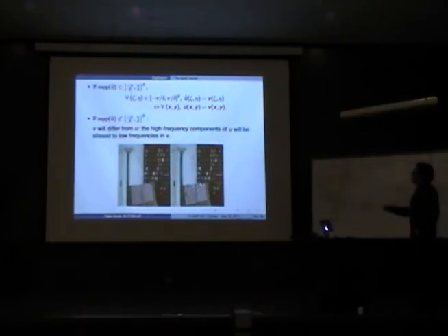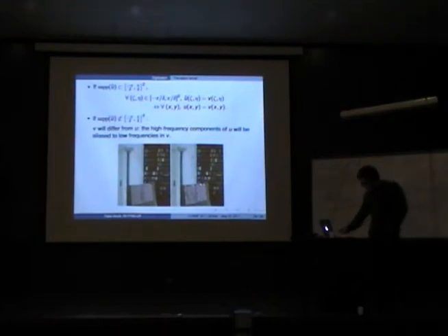If you are not in the Nyquist sampling condition, you have frequency components that get aliased into the low frequencies, and you see these kinds of things, while you should have seen this. So you see there's a high frequency component that gets introduced in the aliased image as a low frequency component.